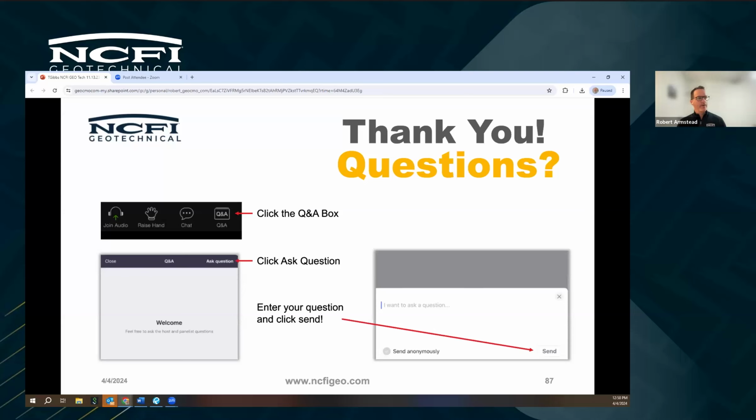Are there testing tools available for contractors to test before and after compaction? Available, yes. Cheap, not necessarily. There are some tools, and some testing works better than others. The best testing methods out there for post inspection, to see if you've accomplished what you wanted to with deep injection projects, are such as dilatometers. They're just not something that a contractor would buy. You're better off just having a company come in and test that.